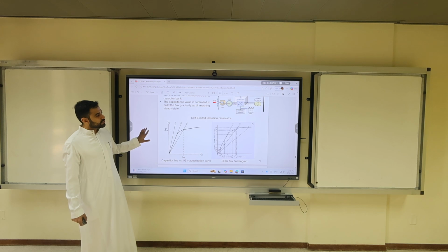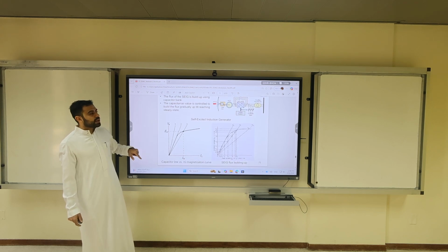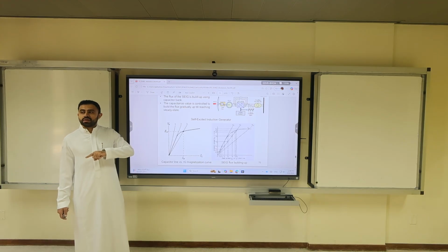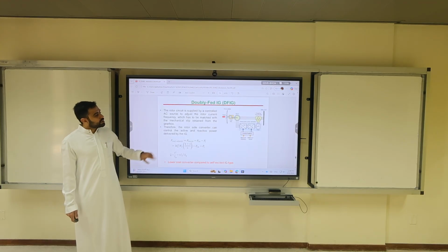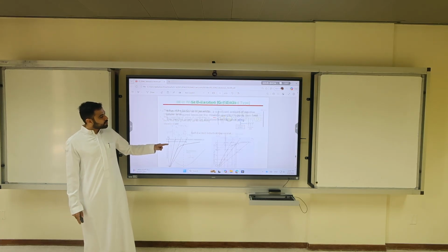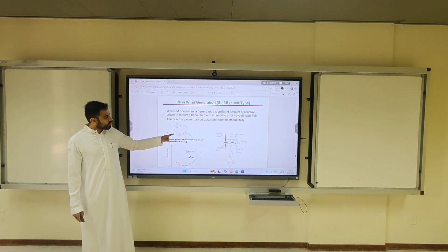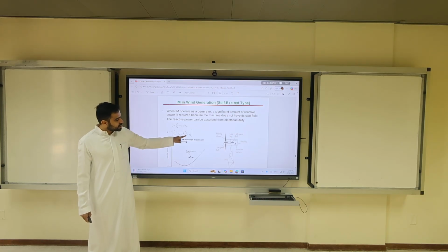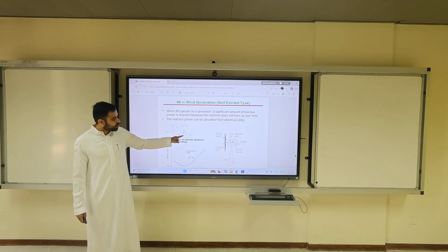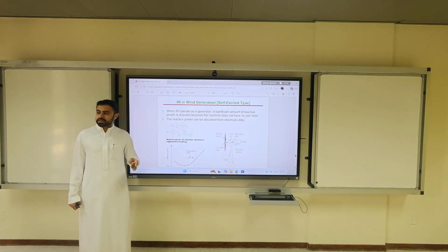So that's the idea, to add build-up flux in the system. And build-up flux has to do with the reactive power. If you look at the other example here, the reactive power is calculated using what equation? V squared over Xm plus this equation, which is the current I2, which is a function of the slip. So if the speed changes, reactive power changes.